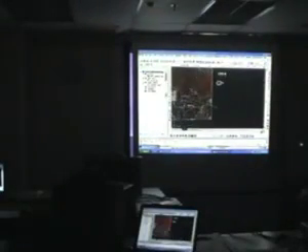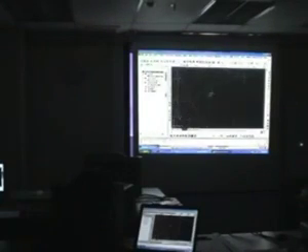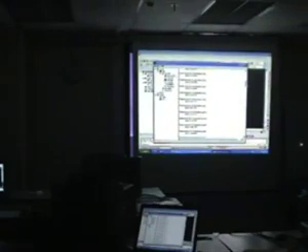I'm just going to minimize this. You can see some extra white lines. So this is actually the watershed boundaries that have been imported inside here. They have assigned numbers. Let's say like 14. If you need to find out which one is 14, what is the equation of 14? Just go to 14. It tells you, okay, this is the area for watershed boundary, number 14.